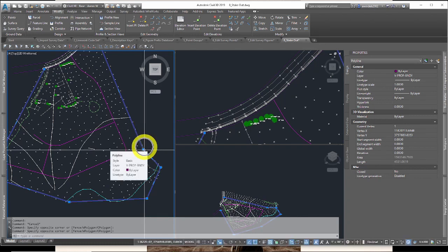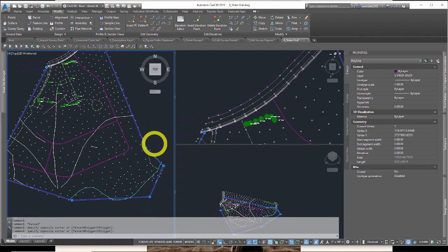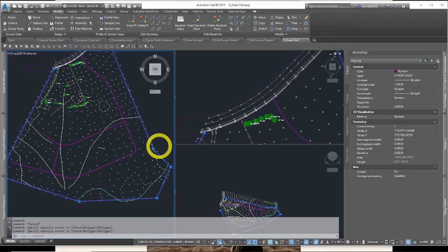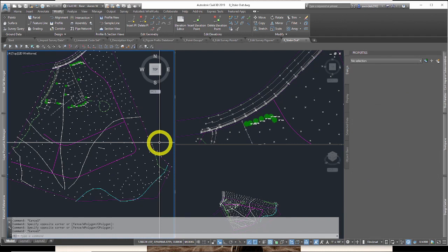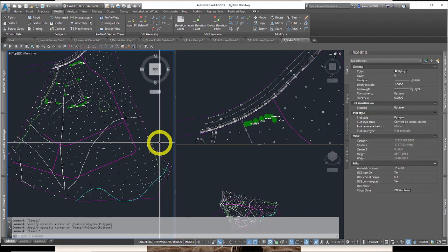Take those points at these vertices and export them out, give them to a field surveyor to put in their data collector to walk around in the field to search for these points. They'll be within a few feet rather than just guessing. When you're dealing with a mile or several hundred feet, you can guess how long it would take to find a really specific property corner without some help. It could take you all day. So that's some reasons a point file might be great.